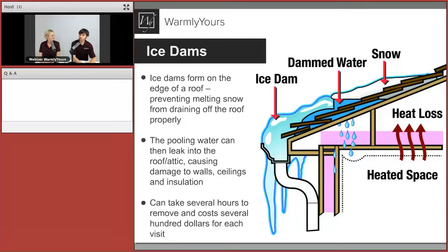Yeah, for sure. The icicles, like you said, they are looking nice, but that's just the exterior part of potentially a larger problem that may be happening right on that overhang of your roof. During your normal winter, you have some snow on the roof, and eventually your heated space gives up some heat through the insulation and melts some of that snow during those warmer days.